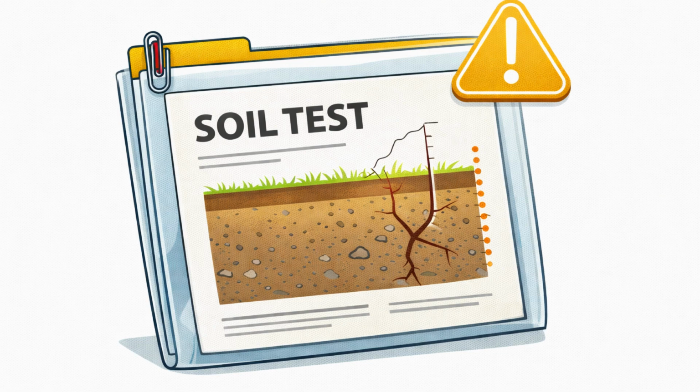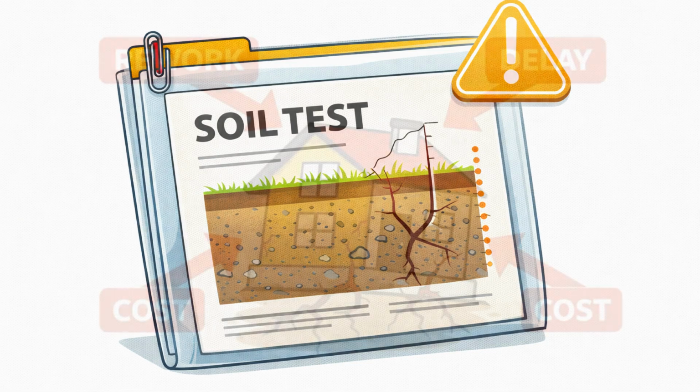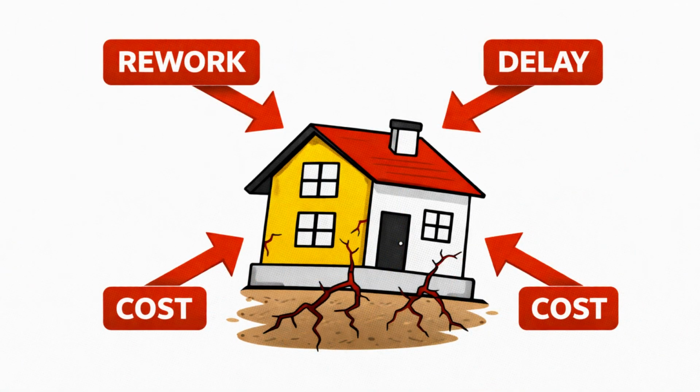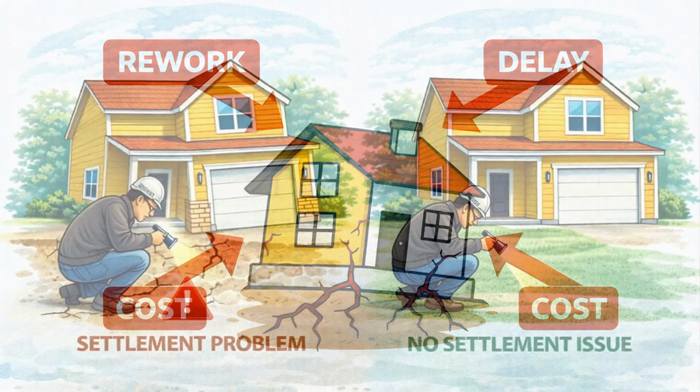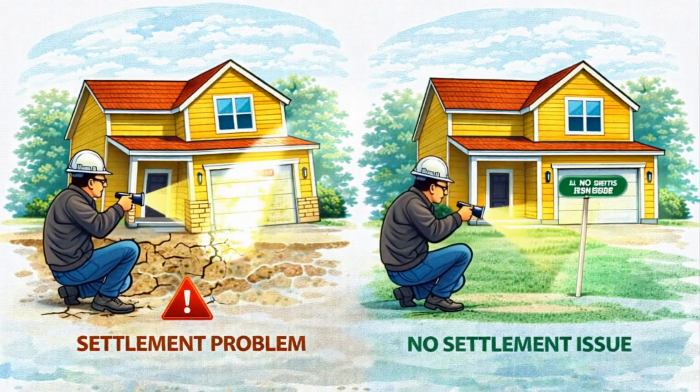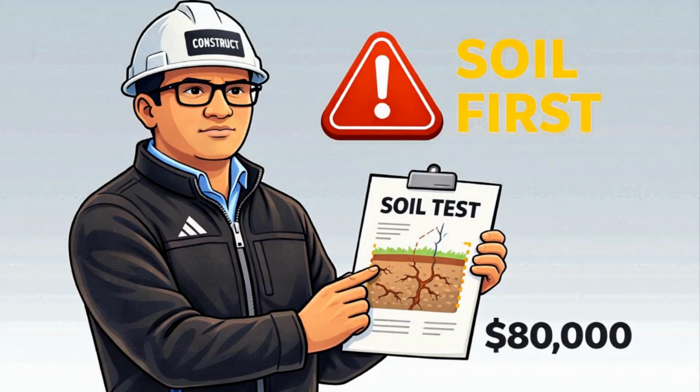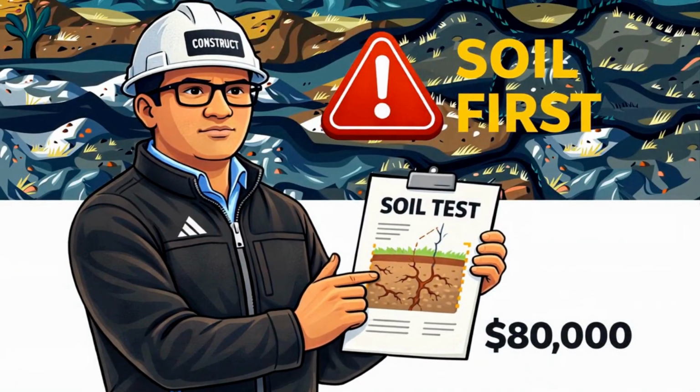When someone says, "I saved money by skipping soil testing," no, you didn't. You gambled. Soil testing is not a cost. It's a risk detector. People avoid soil testing to save a few hundred dollars and lose tens of thousands later because weak soil does not announce itself politely. It announces itself with cracks. Settlement. Doors that won't close. Floors that slope. Water infiltration. If you want predictable cost, start with soil and foundation strategy first.